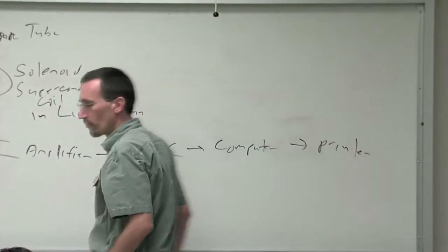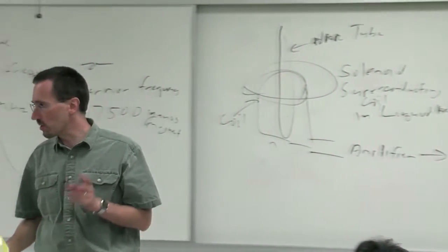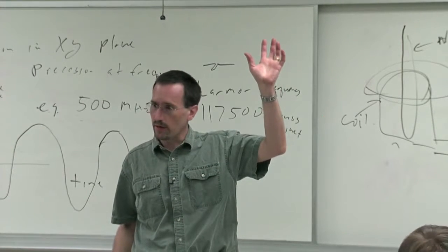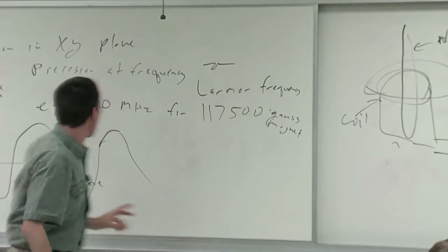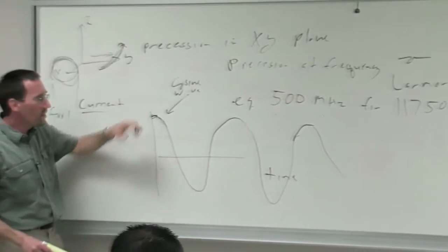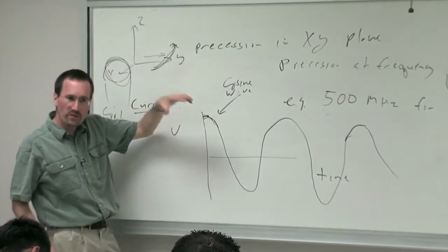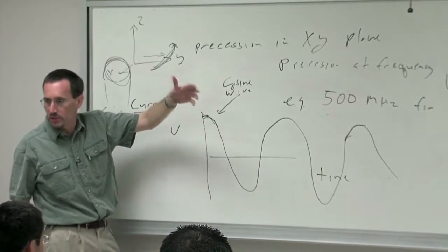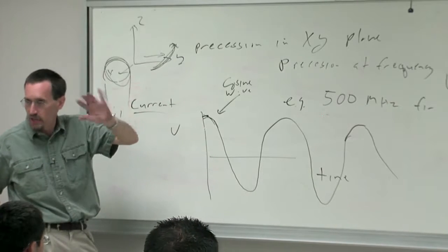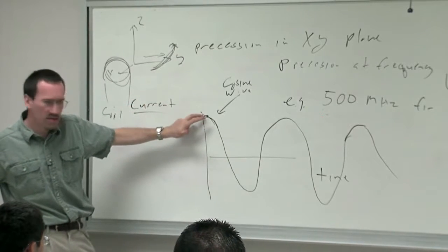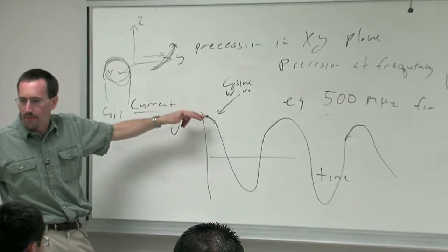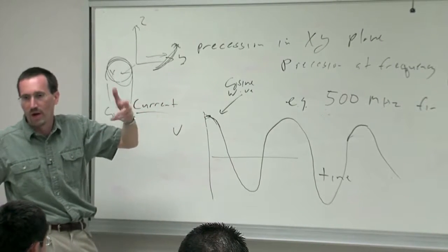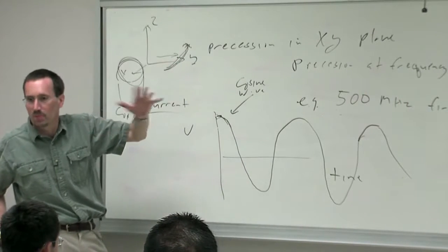And for those of you who've run an NMR spectrometer, you probably know the command RG, receiver gain. Who's heard that one? What you're doing there is basically saying, we want to have as big a number as possible. If we had an 8-bit analog to digital converter, in other words, 8 digits of 0 or 1, you want your biggest signal to fill up that thing to be as close as possible to 1, 1, 1, 1, 1, 1, 1, whatever 8 ones is.